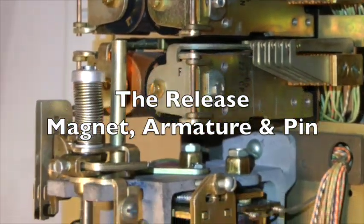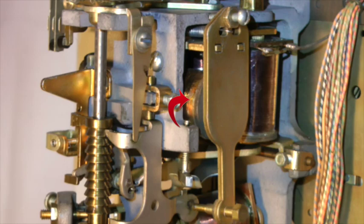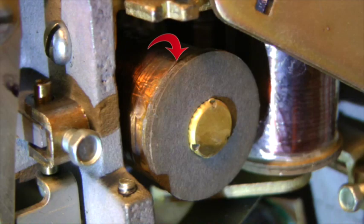There is one other magnet on the line finder that we need to talk about, and that is the release magnet. The release magnet is a single coil assembly. It is energized or magnetized whenever the shaft needs to be returned to its normal released position, and it is de-energized or demagnetized when that action has been completed.